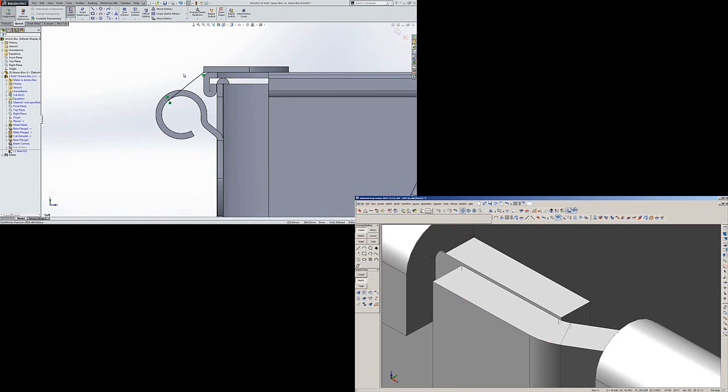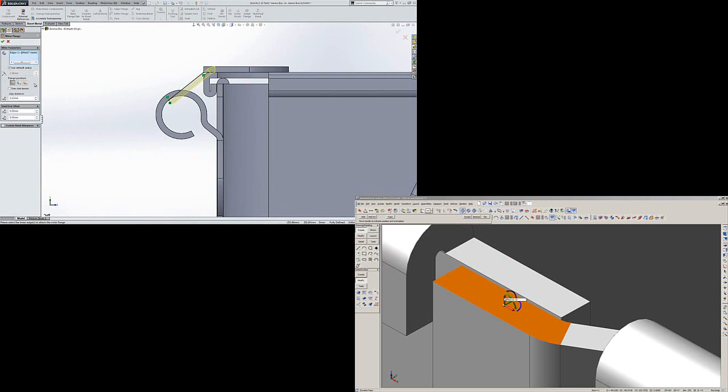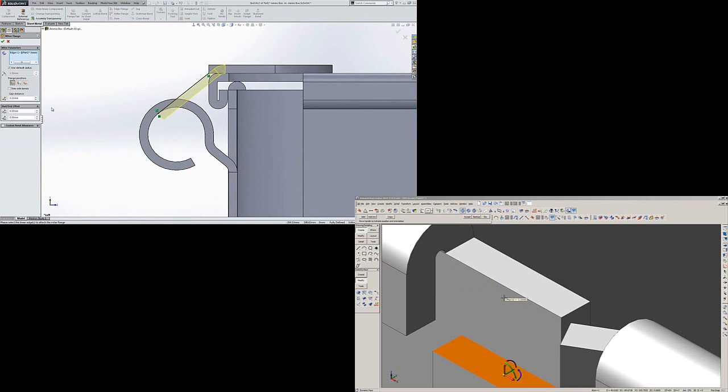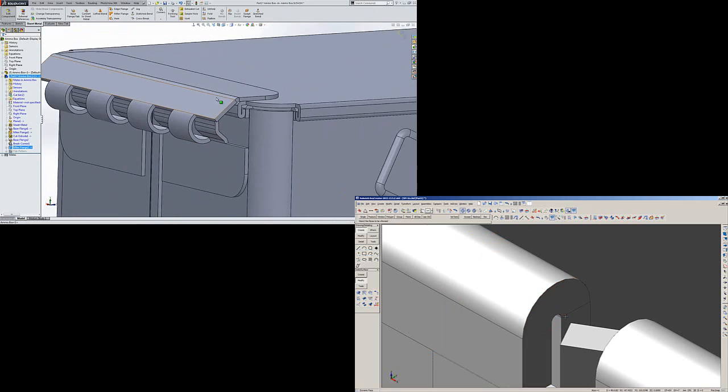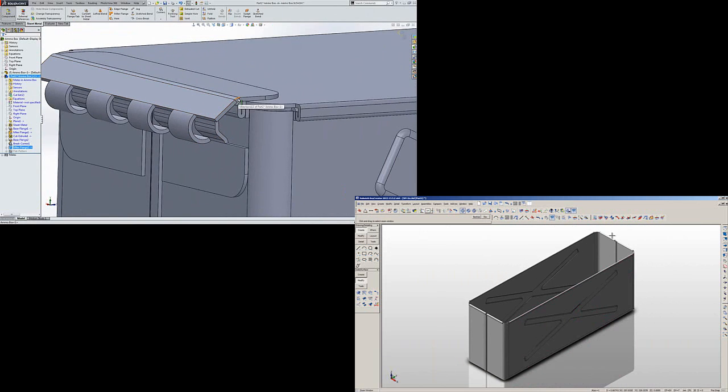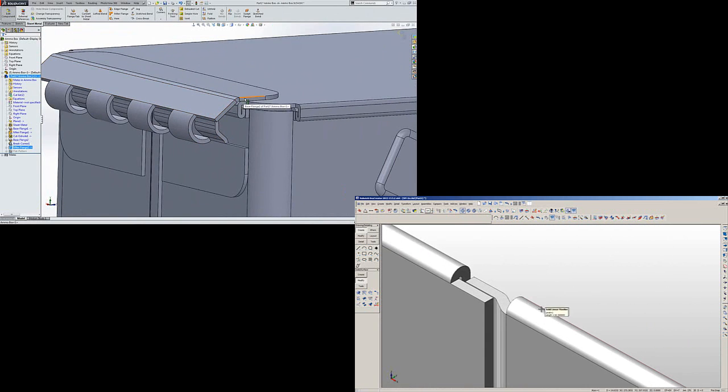Okay, so now that's done, we can go ahead and create our miter flange in our sheet metal like we did before. Now, it's currently sitting a little bit wrong. We want the internal radius to be 1.5, which is default, which is good. We want the flange position to be outside though. So that's actually looking quite good now. We'll accept that. So if we have a look at that, we can see that it extends from one side of our base flange to the other nicely.